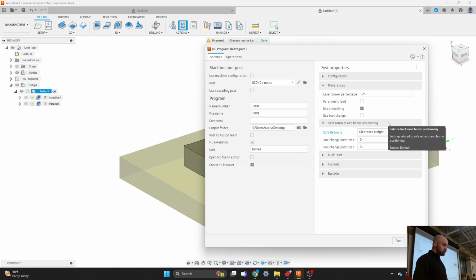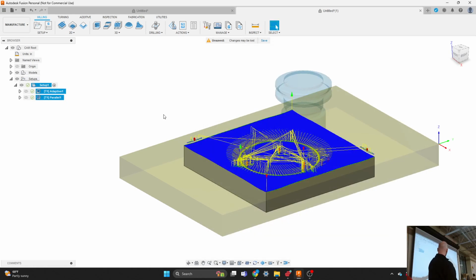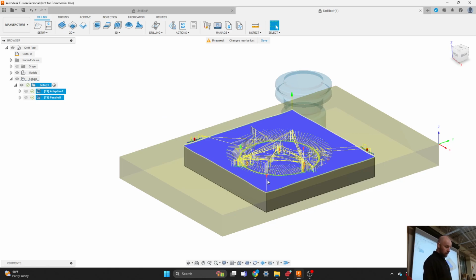So then, assuming we had the milling information done correctly with the speed and everything that you've mentioned, if we have this file, we can export it and then you could load it up and push go. When you load it up on the machine, it will show you all of your tool paths in 3D. On the Mach 3 or UC CNC program, you can zoom in and look at all your tool paths. Cool. All the blue lines will be there.